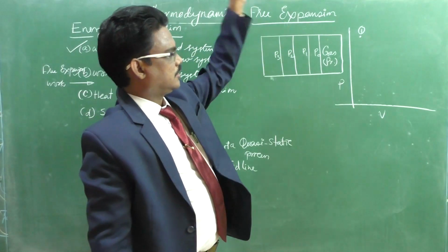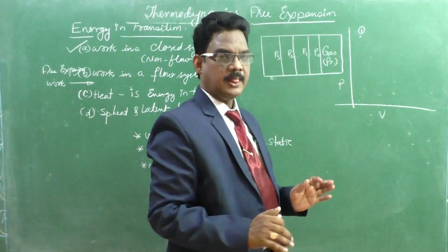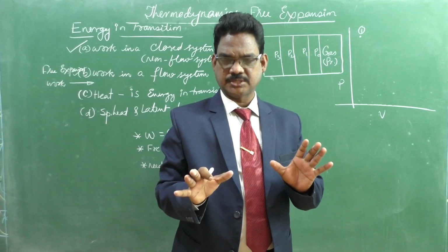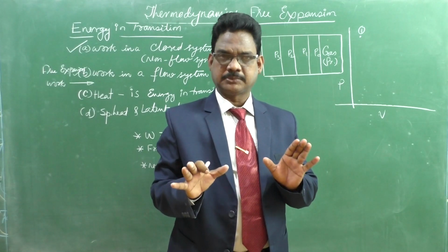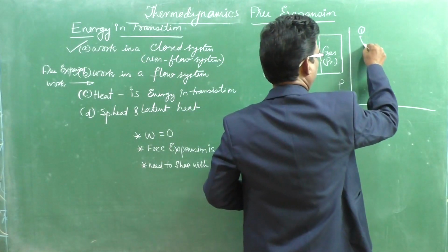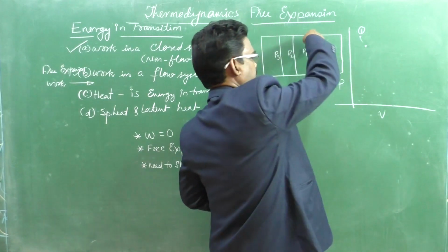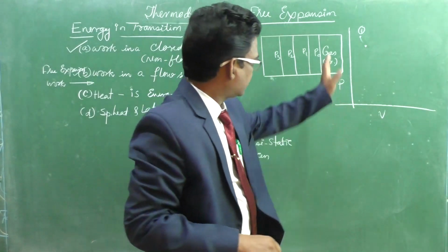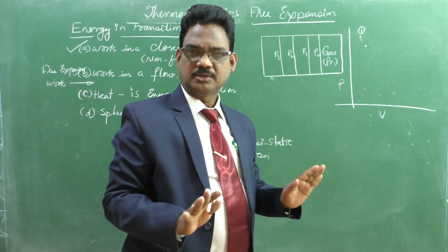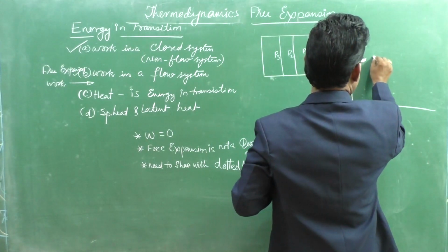Okay, if you remove P0, then the gas expands up to this, and it undergoes a quasi-static process and reaches thermodynamic equilibrium. Up to that we need to wait. Okay, therefore here to here. Next one. After removing the P1 partitioner, the gas expands further. Just wait a minute, it reaches a thermodynamic equilibrium condition. Then you can write that with respect to pressure and volume.